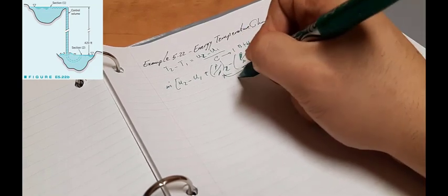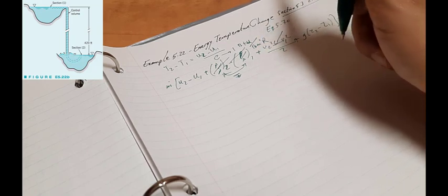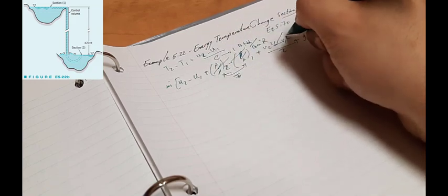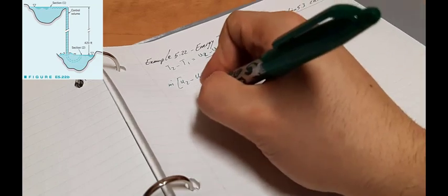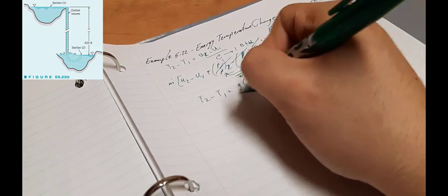As the performance is adiabatic, it's 0, so this means these two are also equal. So they're going to be omitted. As long as we are having incompressible flow in atmospheric pressure, this means that V2 and V1 are also 0, so we don't have any V terms. So at the end of the day, we have T2 minus T1 equal to g times Z2 minus Z1 over C.